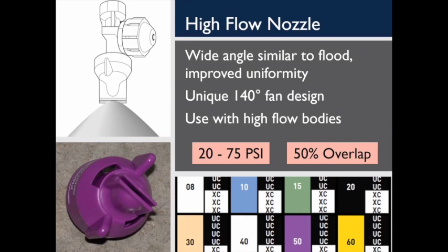In addition to the low drift potential, the high flow nozzle is also capable of being operated within a much wider pressure range than turbo flood nozzles. This is particularly important for sprayers equipped with systems to dynamically change pressure, such as rate controllers, which will be discussed a little later.